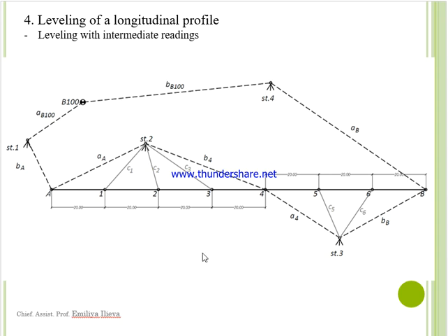So what is the sequence of the geodetic actions here? So we can make a loop leveling line. Of course, we're going to need benchmark. For example, benchmark 100 is going to be the one that is nearest to our facility section. Okay, so this is the reference, the initial point.